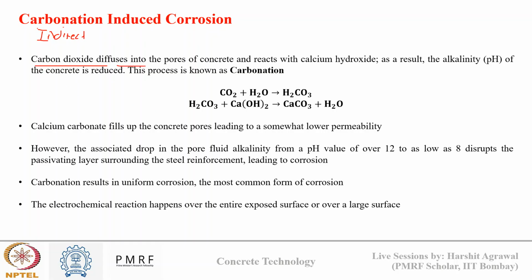CO2 diffuses into the pores of concrete and reacts with calcium hydroxide. As a result, the alkalinity of concrete is reduced, and this process is known as carbonation. So CO2 is reacting with CH inside concrete and forming CaCO3.